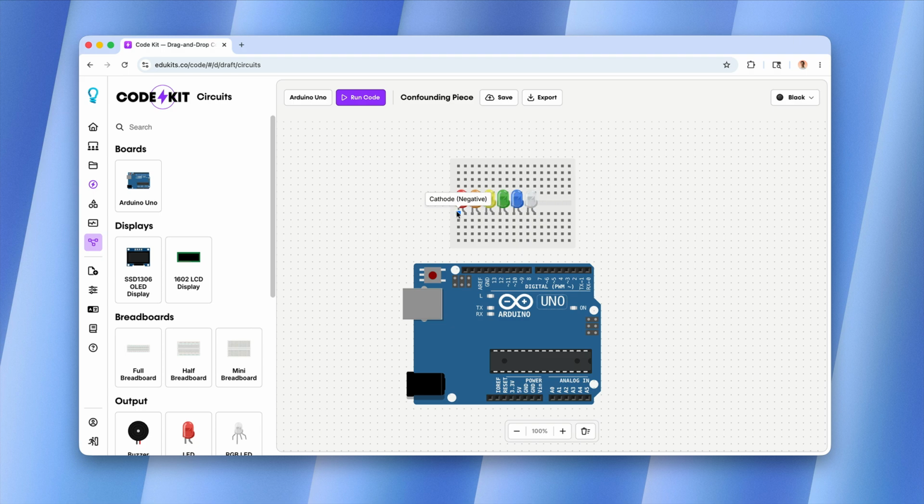We'll start over here on the left, and we see that this one is negative. Now all of this column of the breadboard, all of those connections, all those terminals are actually joined together. So if we connect this particular input of the breadboard to ground, that is actually going to link up the LED because it is in the same column. Next, we want to connect this negative to this negative, to this negative, and so on. We can just do that.